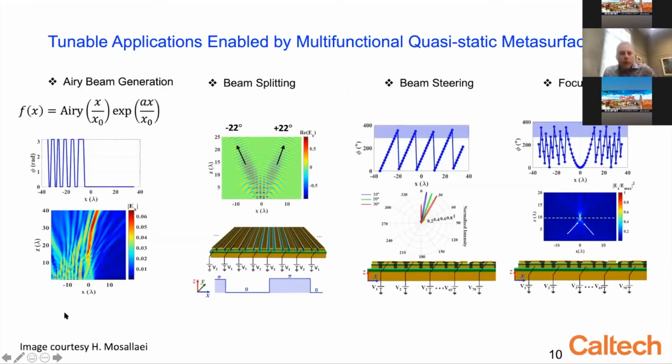And so if we think about quasi-static metasurfaces where the scattered wave is essentially the same as the incident carrier wave frequency at lambda incident, we could think about now using reconfigurable antenna elements to create spatial phase gradients and amplitude gradients, and allow the phase profile to create the conditions to create an Airy beam or to create a diffracted beam from an array of nominally specularly reflecting elements before I apply the voltage.